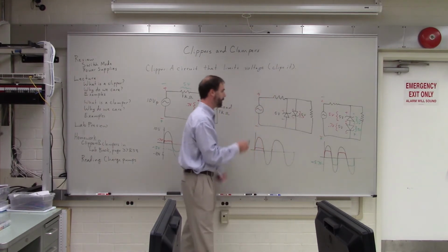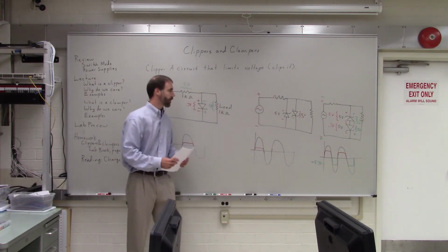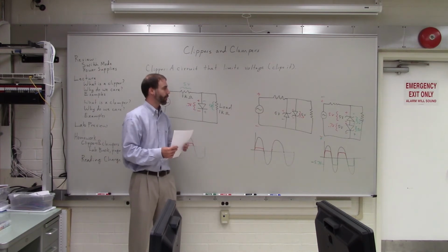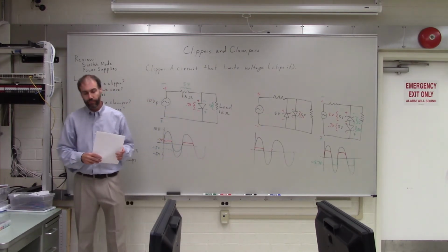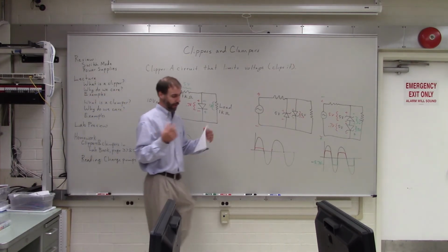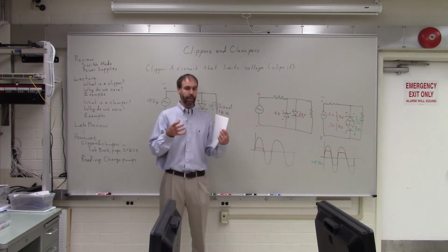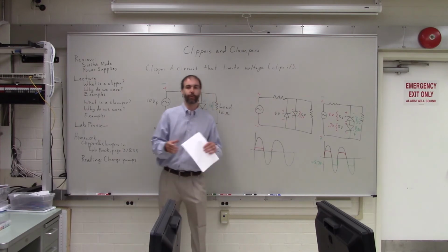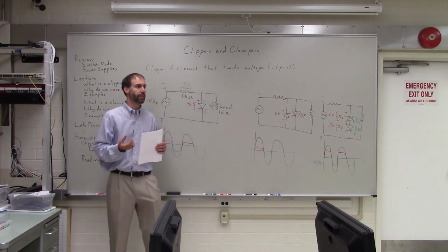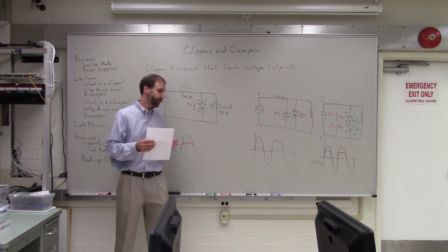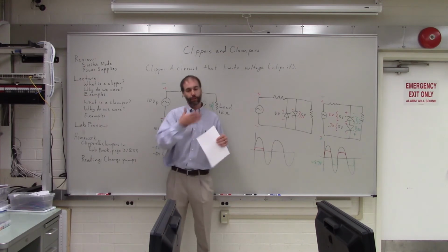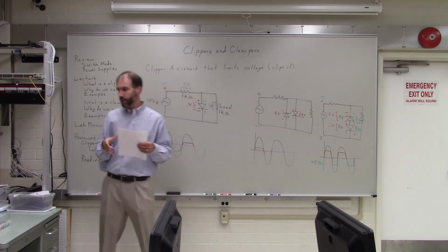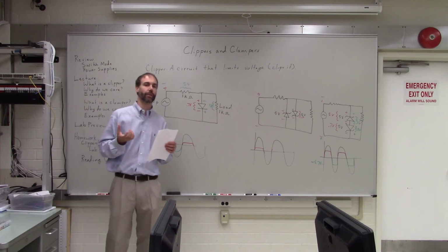And this type of circuit is actually used quite a lot in parallel with motors. What happens with motors is that a motor consists of a lot of coils of wire that are electromagnets. But what's another name for a big coil of wire? What type of component is made out of a big coil of wire? Yeah, inductors. Transformers are also, but in this case, just a single coil of wire is like an inductor.